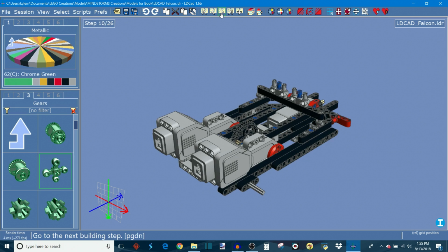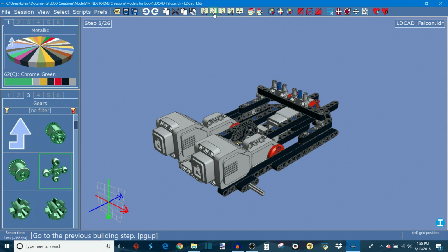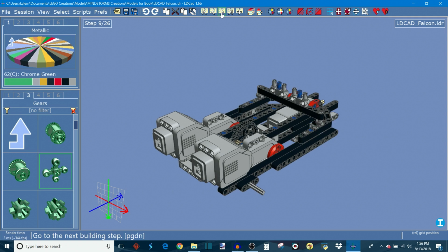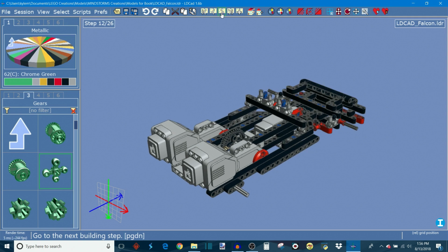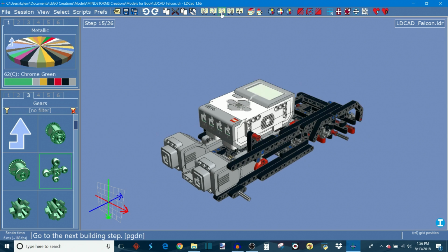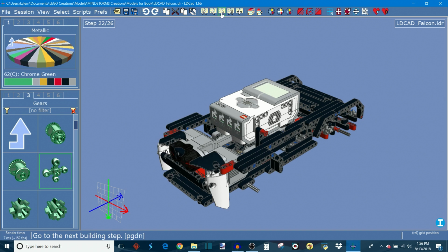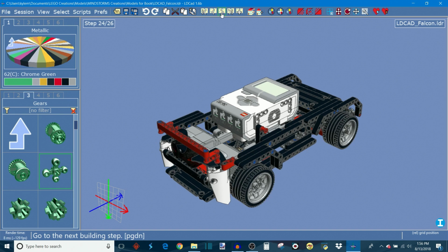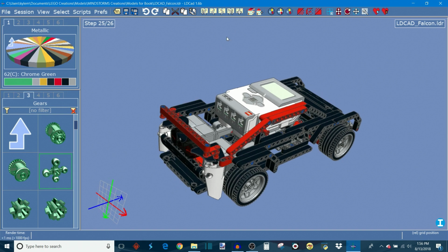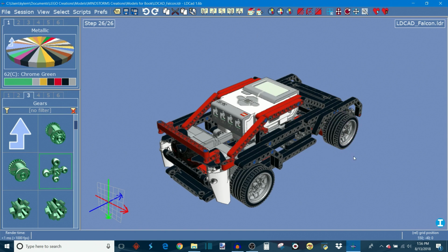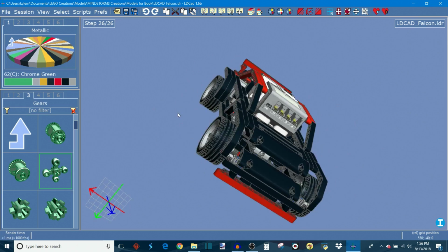And again, this is really important because it shows you a few steps at a time, so you can use this LDraw file as kind of like a rudimentary building instructions, or you can export this into software like LPub to make actual Lego quality building instructions from. So going through all the steps, this is what it looks like. And it's important when you're grouping steps that you just choose a few elements at a time, otherwise you'd be defeating the purpose of steps by making them look too overwhelming.